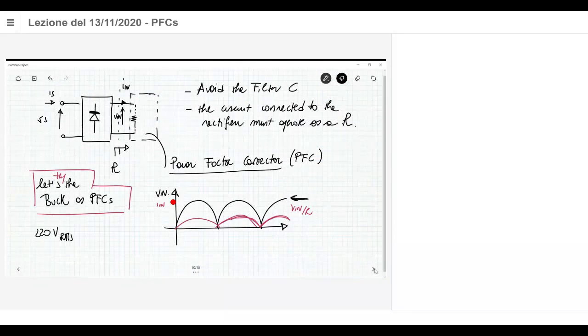And then you have to consider that you can have plus 10% as a nominal variation of this voltage, which gives you something like 260 volt root mean square more or less. So the peak value is square root of 2 times 260, so you can have 360 volt. Okay, more or less. You can have a better computation, but typically the peak value here can be 360 volt.